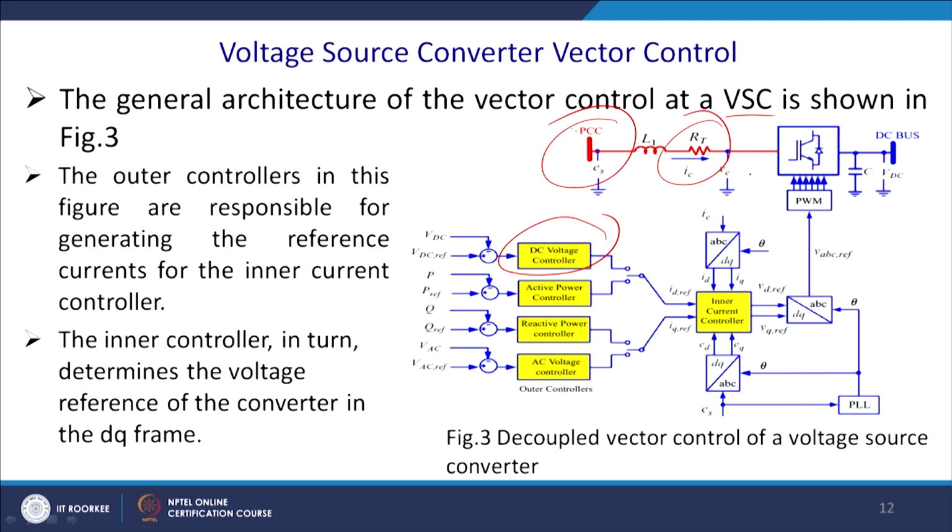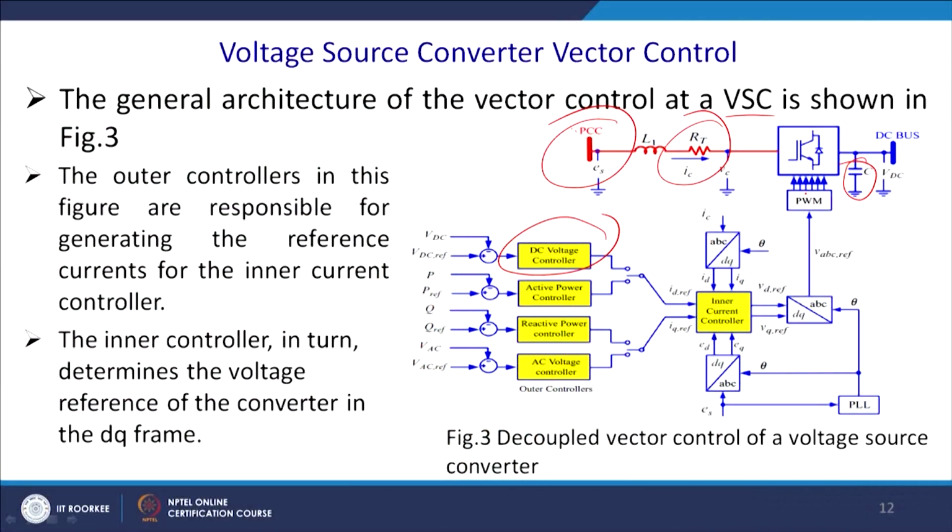Even if you withdraw the pulses of the PWM, you will get some voltage here. That will be the 3 phase rectified voltage, 6 pulse voltage, 3 root 3 Vm by pi. So, this kind of expression you will get. So, you have to take it 20% above by switching, because essentially it is seen as a boost converter if you look at it from that side.